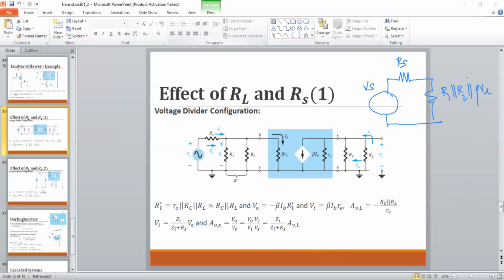So then you can simply take the expression for this Vs, and similarly you can map this output. So this is very simple. This is isolated from your input, so you can treat your output separately and get an equation for V out, and simply combine these two equations. One you took by considering your input circuit, and the second one you take from this output circuit. You can just combine them and get the end-to-end voltage gain for this kind of circuit, where you have this load resistor and an internal resistance for the source.